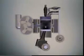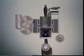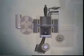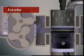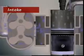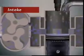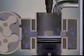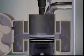Let's look at the two-stroke diesel engine cycle. Once again, the 5 key events occur, but in a different way. At the start of air intake, the piston is moving towards bottom dead centre at the end of a power impulse. The piston uncovers the inlet ports and the blower delivers fresh air into the cylinder. The exhaust valve opens. The piston reaches bottom dead centre and starts its move upwards.